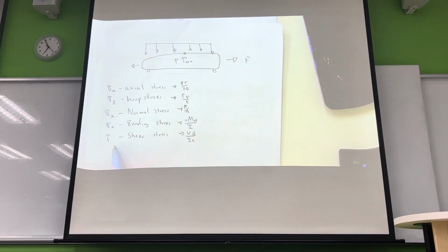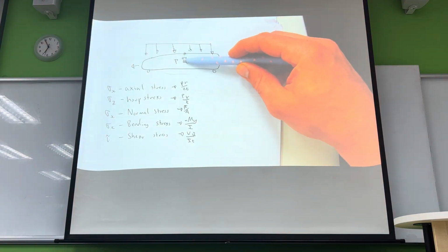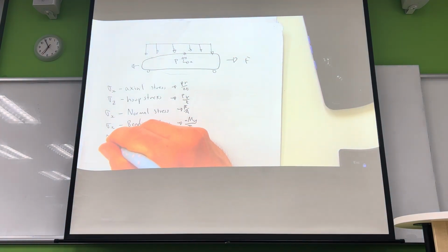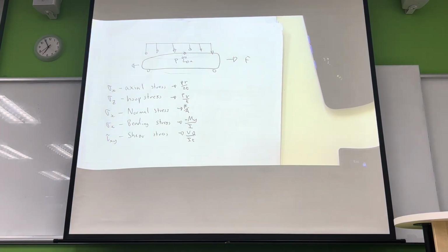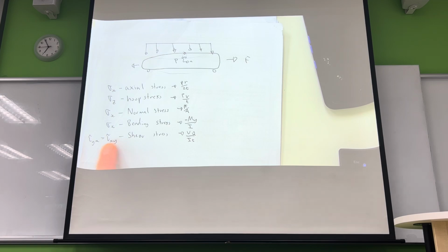And that shear stress we talked about yesterday is on the X face in the Y direction. So it's vertically going up and down, but it's on the face which is perpendicular to the X direction. So if we write that as XY, that is also, I'll talk about that bit later, going to be numerically the same value as the stress in the X direction on the Y face.